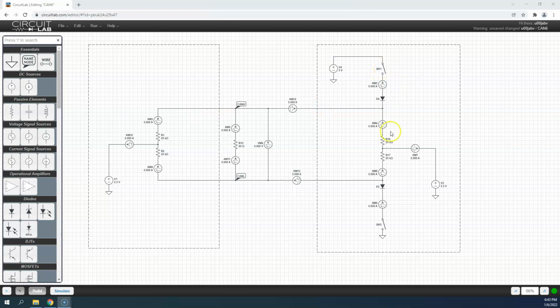This one I've put physical switches on to allow us to drive to the dominant state. The other one we're just going to leave in the recessive state. I just didn't put those switches in there to simplify this. So we can look right now. The voltage differential is approximately 0 volts between CAN high and CAN low. Well, it's actually exactly 0 volts because my simulation is perfect.